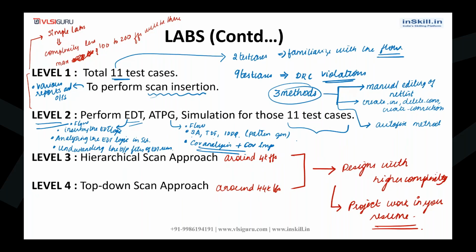Okay, and then we will also understand generating patterns: pattern generation with TDT, and bypass pattern generation. All those things we will understand in our ATPG lab. So we will understand the flow, and then we will be doing the pattern generation for these three fault models in our lab: stuck at, TDF, and IDDQ.